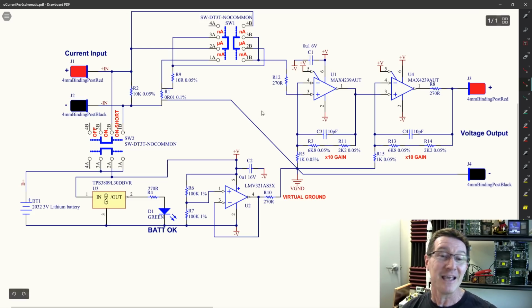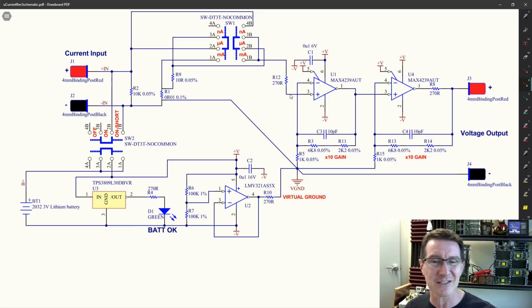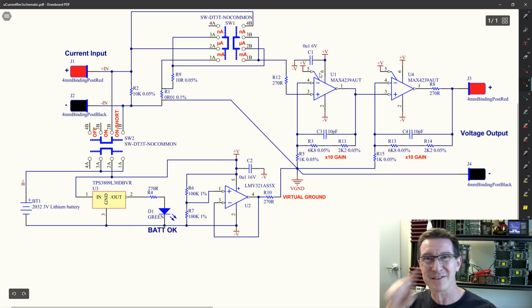Try and find the best. In this particular case, it's a chopper amplifier. I won't go into that, but that's how they get the low offset voltages. It chops at a certain frequency. In the case of the Max 4239, it's about 15 odd kilohertz or something. So there's a little pole response in there, so it has disadvantages. But chopper amps give you extremely low offset current, almost negligible. But yeah, let's take a look. Is there anything better these days than the Max 4239?